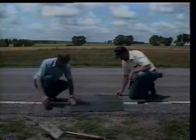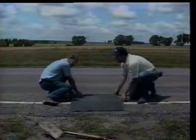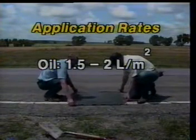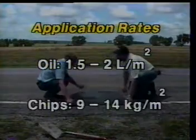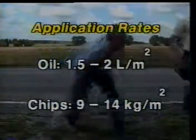Both the oil and chip application rates should be verified. As a general guideline, you'll need between 1.5 and 2 liters of oil per square meter of surface, and between 9 and 14 kilograms of chips per square meter.